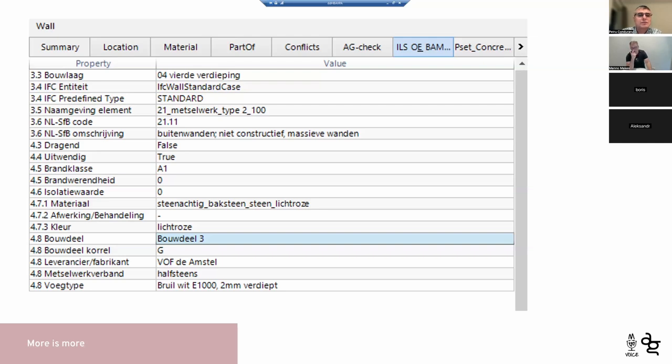It sure is, and we do have a lot of things for that, like the bSDD, buildingSMART Data Dictionary. We have add-ins for Revit as well to put it in the model. Because what you see here, this is building story. This is the entity, predefined type. This is IFC name. This is a classification code. This is load bearing, is external. This is fire rating, thermal transmittance.